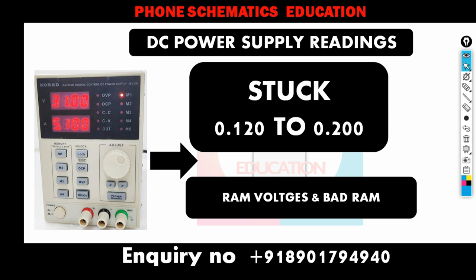Sometimes this problem goes to the CPU, because if the CPU does not respond to the RAM, there is a communication drop, same as with MMC. Nowadays, the stuck problem is also caused by the CPU, because of communication loss between the CPU and the storage IC or RAM IC, and then you will see these stuck problems.